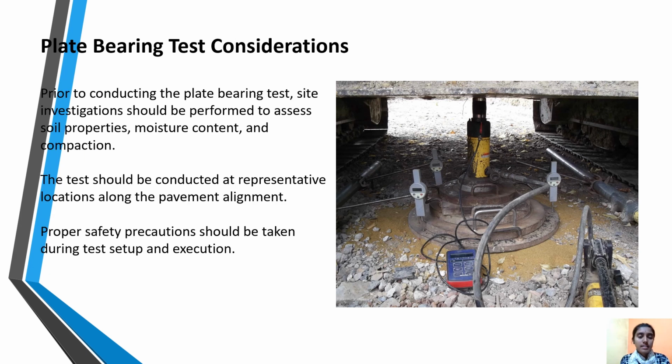Plate bearing test considerations. Prior to conducting the plate bearing test, site investigations should be performed to assess soil properties, moisture content and compaction. The test should be conducted at representative locations along the pavement alignment. Proper safety precautions should be taken during test setup and execution.